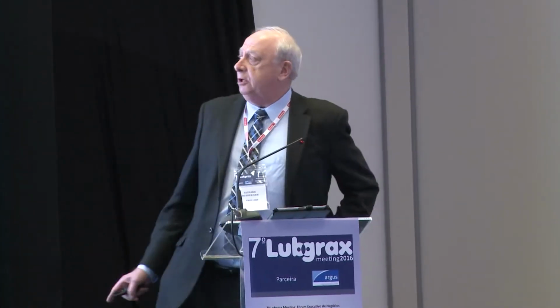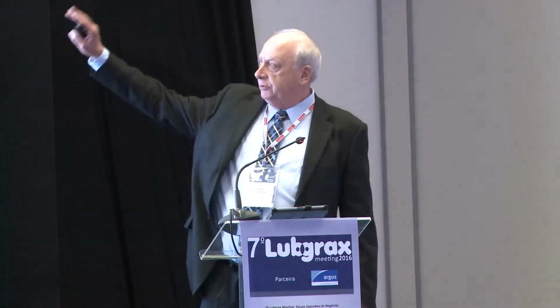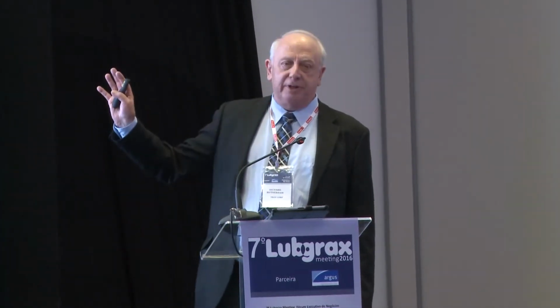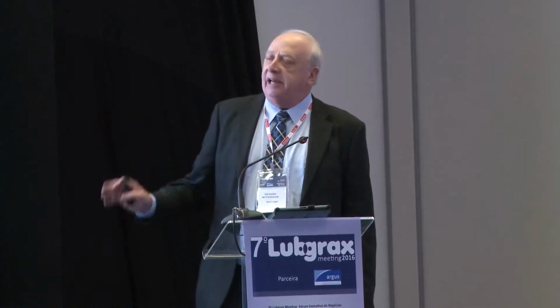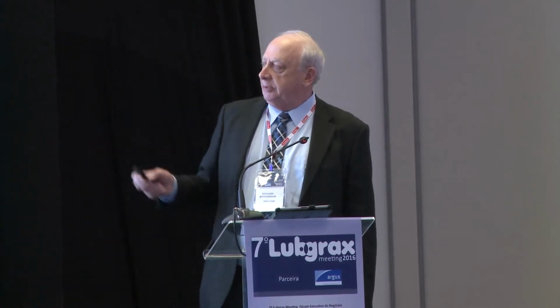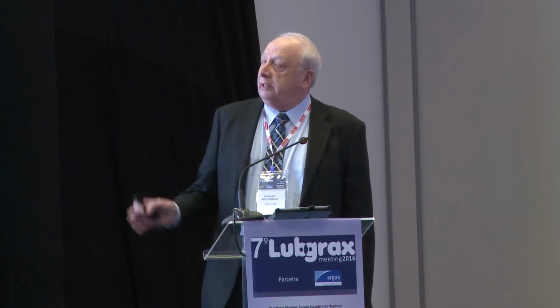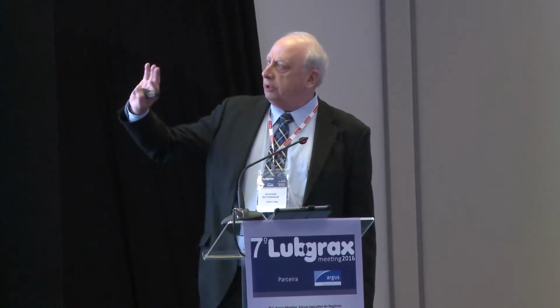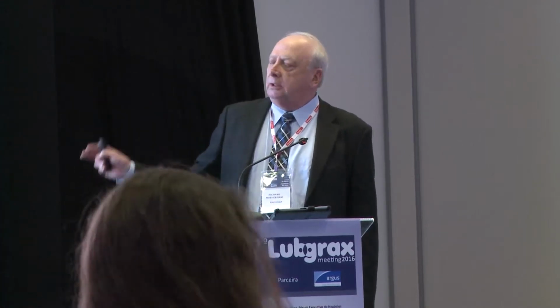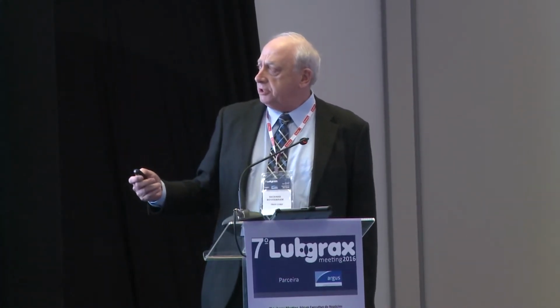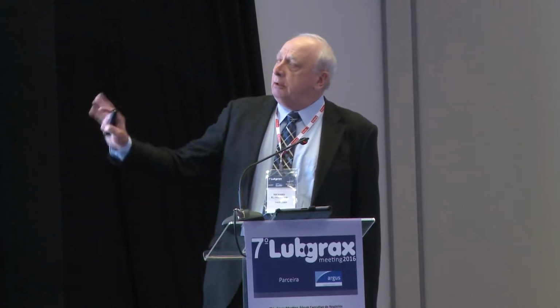So my objective this morning is to review sources of microbial contamination, the impact of microbial contamination on the fluids, and talk about some strategies to minimize and control microbial contamination. As you've already heard, water is the biggest component of the fluid, and even if it's treated, it's not sterile. So it's a major source of contamination.